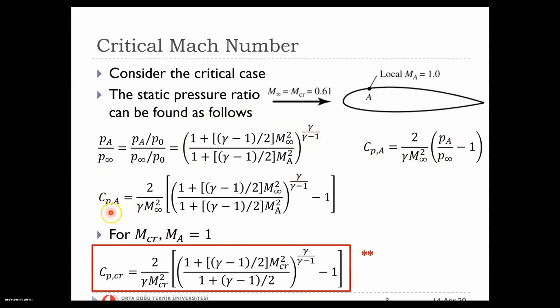It actually tells you the relation between the pressure at point A and the velocity at point A, as you can see. So you can consider this as a kind of corresponding expression for a Bernoulli equation in the compressible flow. Of course, the Bernoulli equation applies in incompressible flow. It also gives you the relation between pressure and velocity locally at a point, and here we also have a similar relation. For point A we can have the relation between velocity and the pressure.